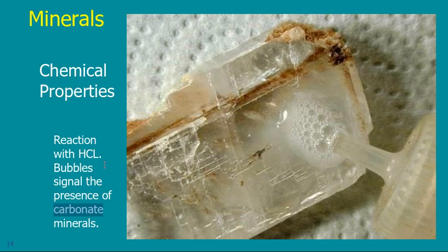When I go to the site, I will take with me a glass bottle filled with HCl. And when I go, I just put a few drops on top of the rock. If I see something as if I have boiling and a reaction, bubbles coming up, it means that there are carbonates in this material. I say that no, this material cannot be used in our building.